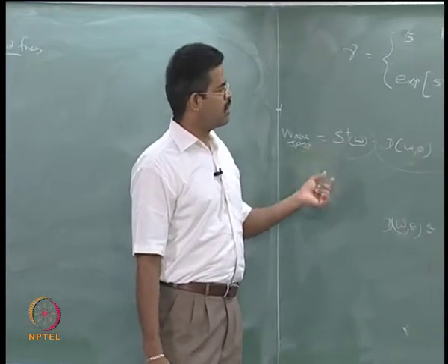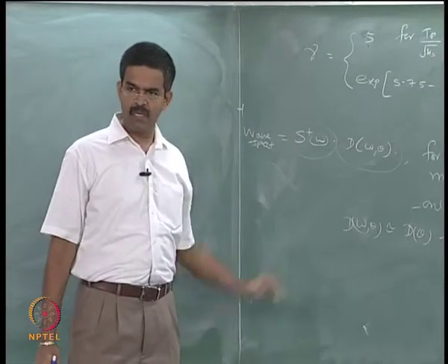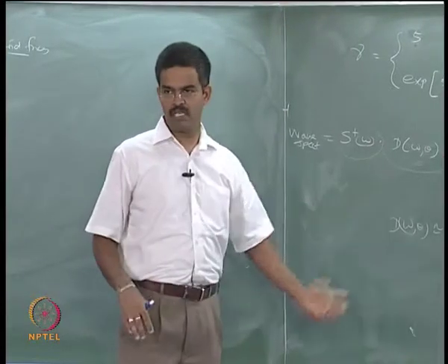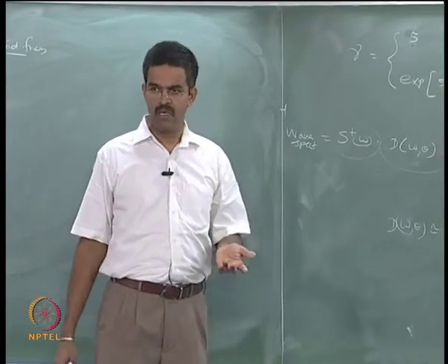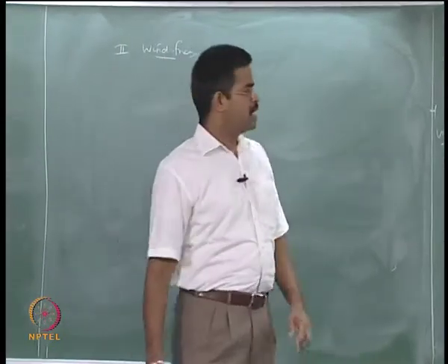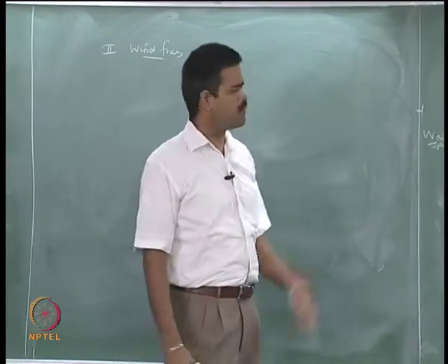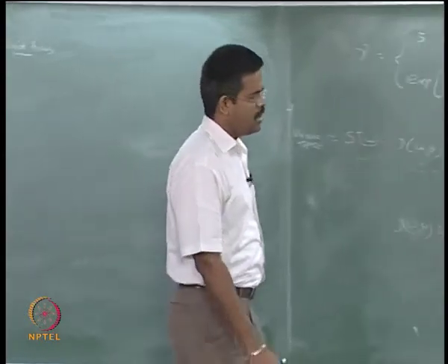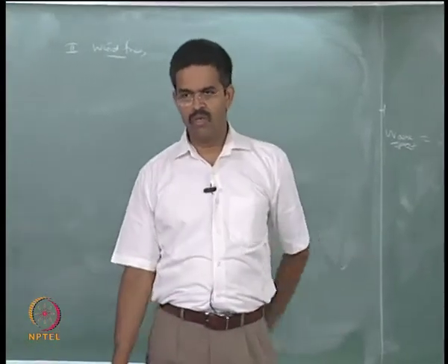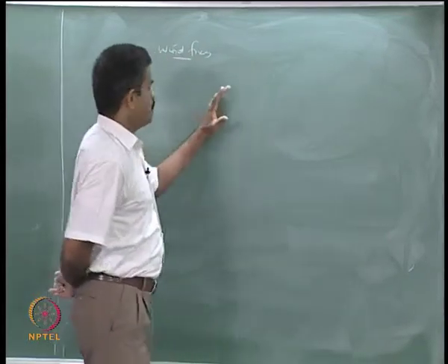Of course, when we talk about the loading, we are amounting to what we call a spectrum. We found there are different spectrums available in the literature, and we have seen the commonness between them, such as the one-parameter PM spectrum, or the modified version which has two parameters, omega p and the significant wave height. We have also seen how the JONSWAP spectrum can be brought down to the Pierson-Moskowitz spectrum. Therefore, people commonly use the JONSWAP or modified PM spectrum in marine structures for finding the force. This is about wave loading. Let us come to the wind forces.